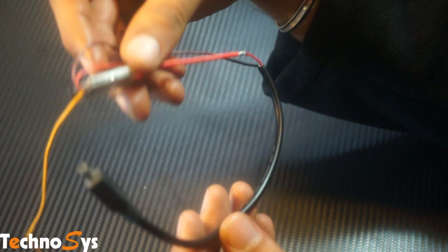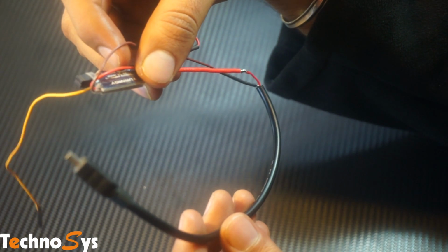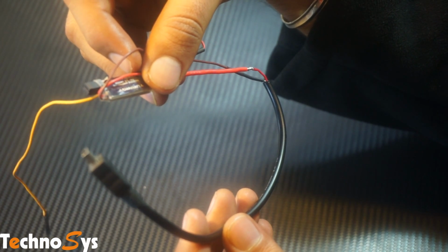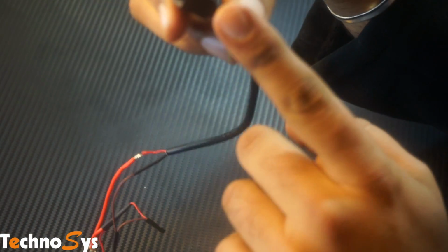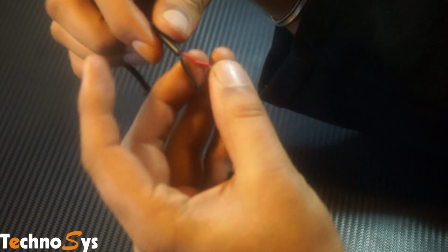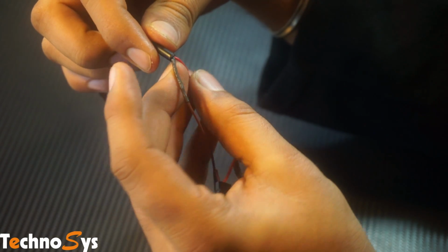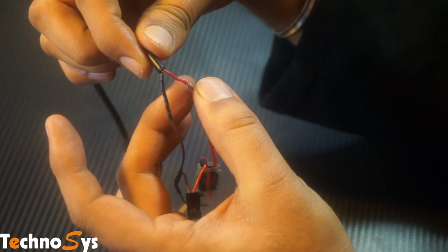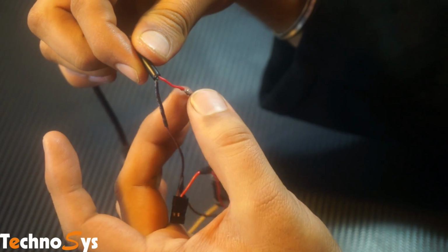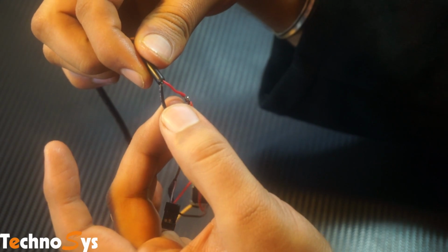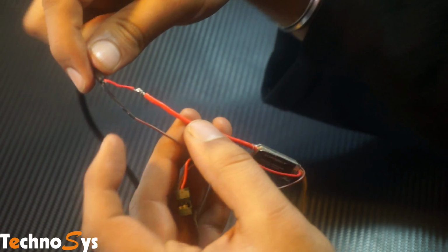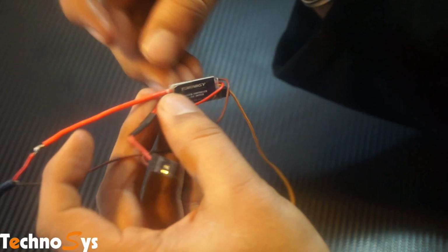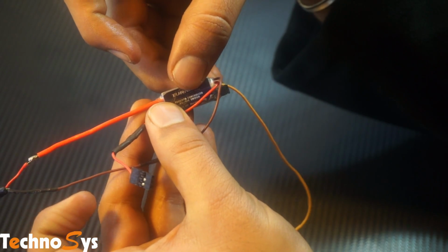So this is the kind of cable you'll have to make for triggering your Canon PowerShot with PIXHAWK. This is a regular USB connector. Of course, we have cut it from here and eliminated and cut the rest of the cables, and we're going to use just the positive and the negatives. The positive is the red cable and the negative is the black cable. So we'll first follow the positive cable. It has to go here into the receiver switch, and that's it.